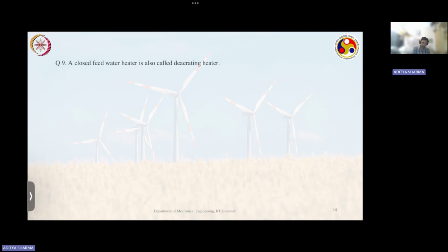So this was about zoning of closed water heaters. A closed feed water heater is also called a deaerating heater. Whether this is true or false? Deaeration is related to your open feed water heaters and not your closed feed water heaters. Correct? So this is a false statement. B.